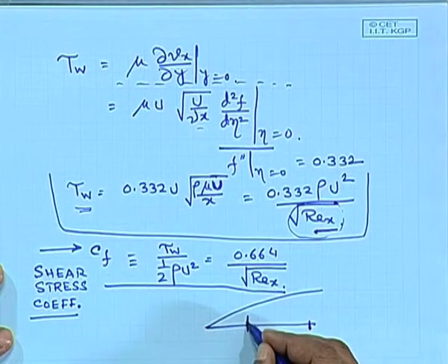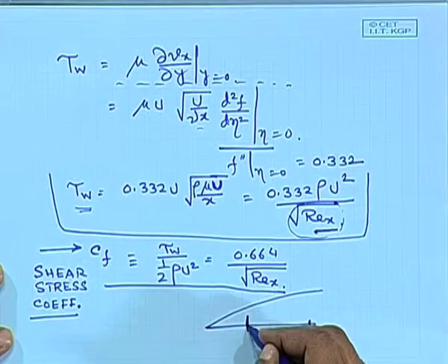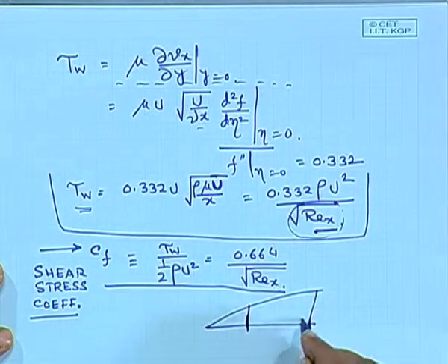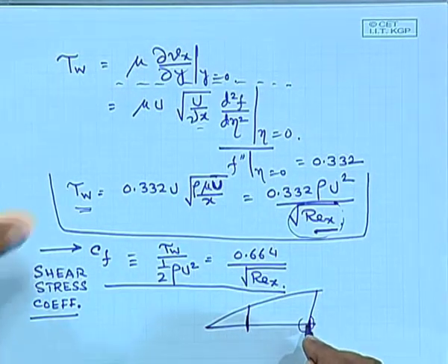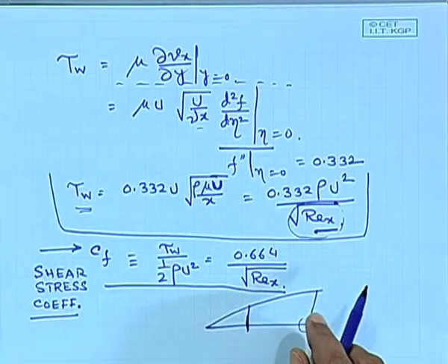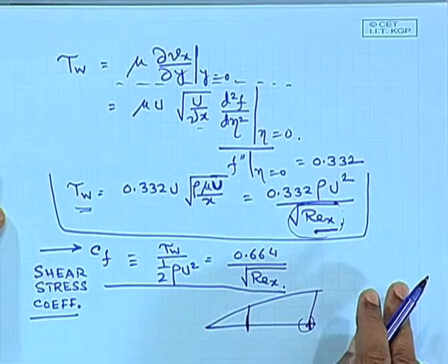Over here the velocity gradient is more compared to the gradient over here, since it changes from 0 to v over a larger distance, so the gradient is less. If the gradient is less, then shear stress has to be less. So, whenever you encounter any formula, see whether or not it is consistent with your understanding, which it is. Do you have any question up to this point?